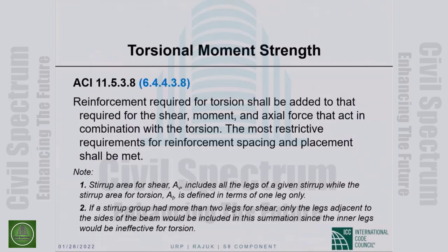This is not a trivial statement. This is very important. For shear reinforcement, we have restrictions on spacing, size. For flexural reinforcement, and it will go by the most restrictive requirements. For reinforcement, spacing and placement shall be met.